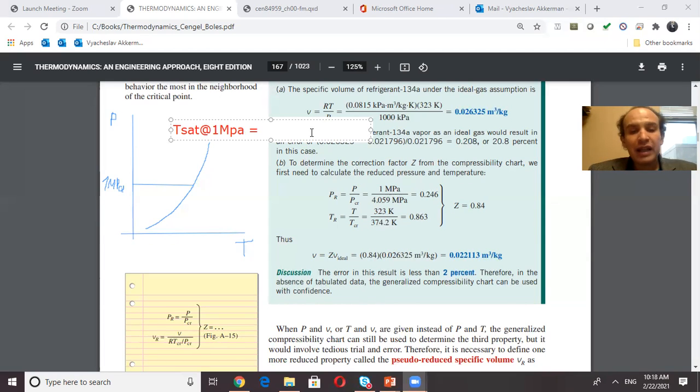If you use table A11, there will be a small problem, because in table A11 there is no value for 50 degrees Celsius. There is a value for 48 and 52. You can interpolate, of course, but we had better use pressure. So you go to table A12, and let's find the saturated temperature at this given pressure. What is it? Something like 39.4 degrees Celsius.